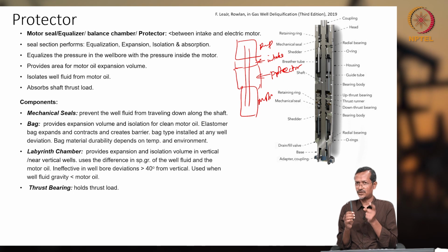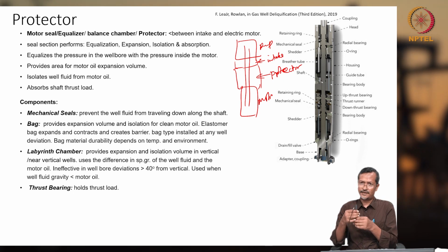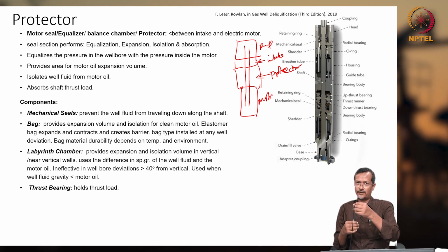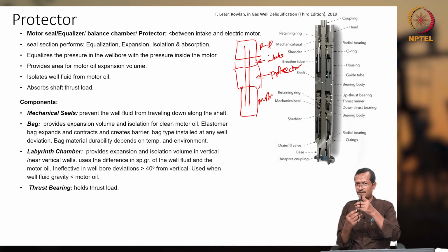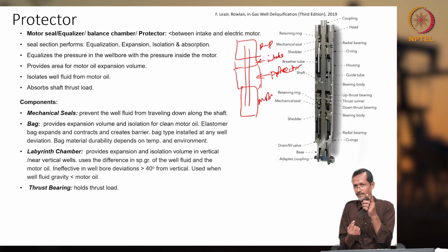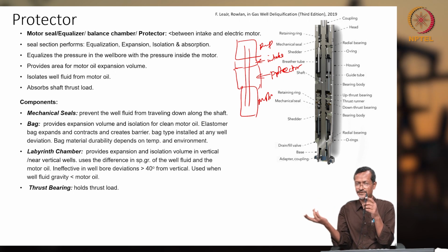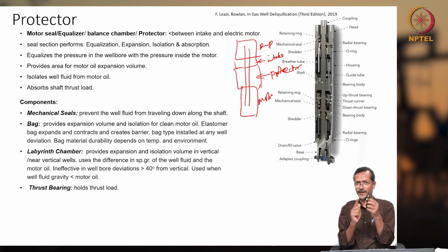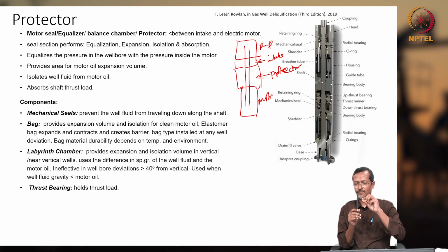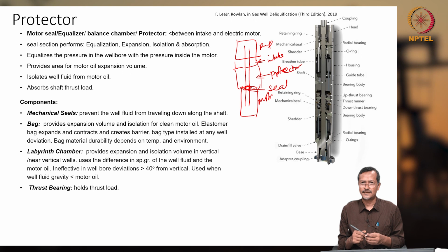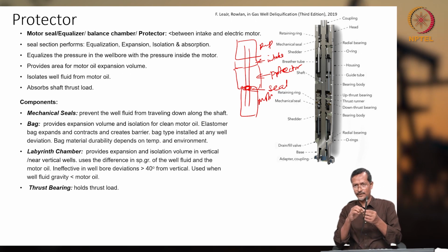Subsurface temperature also changes because of the motor running. Let's say initially, during the installation stage, the motor is inserted at low temperature, and when you give electricity, the temperature goes up. Temperature going up means there will be some expansion of the whole system, and the liquid will also expand. Because of this high temperature, some liquid will try to go out of the system, and after a long working life, the motor seal will get damaged. Seal damaged means the whole liquid will go out.